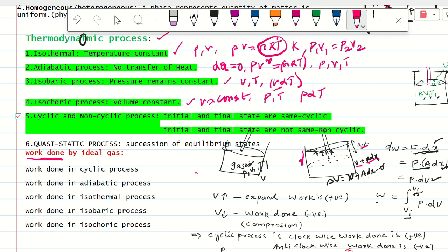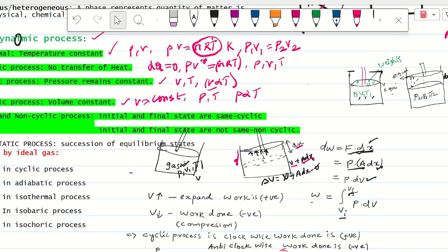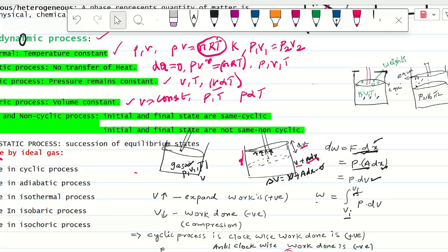And in a quasi-static process, which I forgot, I am explaining that. Here the piston has some weights, and the initial state has pressure P1, volume V1 and temperature T1. Now you slowly remove a small piece of weight, then the piston rises to some height, delta X, and again it becomes an equilibrium state. If you vigorously or suddenly remove more weights, then maybe the piston will come out, and gas exits and leaks out.